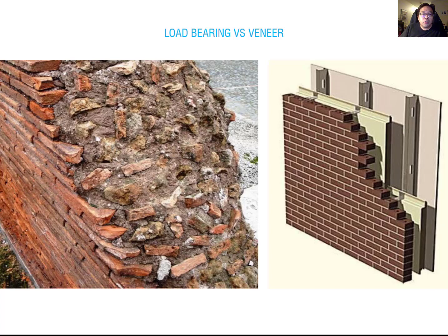So the load-bearing wall requires huge thickness because it has to support the building weight. And it has to work as the structure member. But nowadays, you cannot use this thick wall for the project because when you use this thick wall, it has more cost for the construction, and then you also lose area for your design. So for this reason, you have to consider an efficient depth and efficient size for your wall design. So that's why instead of using the brick wall as the structure, you might consider a different material for the structure member, and then the brick is only for the decoration, which is only for the skin.